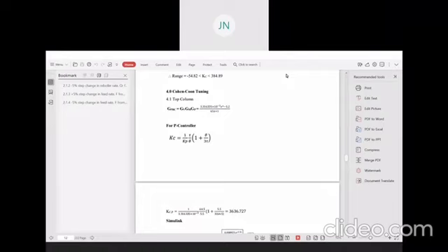As for P controller, we can find Kc by using this formula shown here. And Kp is stability criterion, and tau and theta we have already found in part 1, which my friends have explained. We just substitute in the values to get the value of Kc.